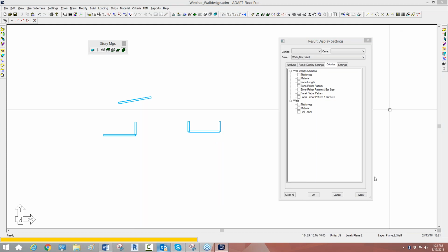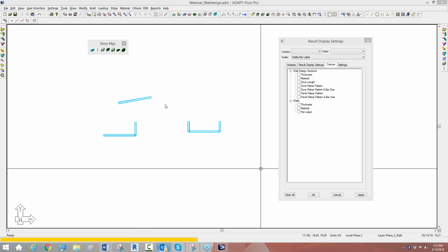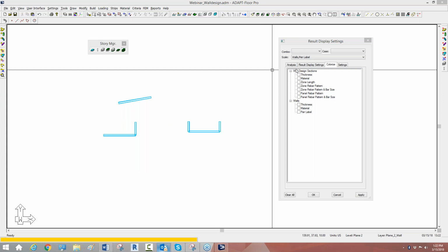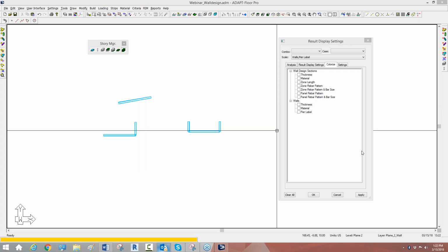Now there's another question. The question is, can you modify combos in the IMP file, or is it simply an export from ETABS where one has been created? You could, Pavel. If you create the file, you can open it in Notepad or some other editor, and you can manipulate the file before you import it into Adapt, into Builder. It requires that you maintain the format and the syntax for the IMP file, but you can manipulate and generate it or make changes to it.